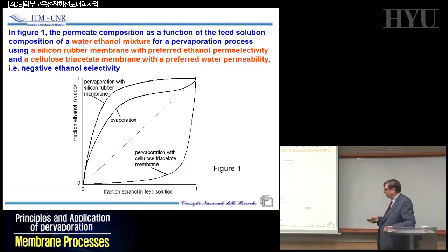This kind of process is utilized today in some areas. It's not standard. There are no big plants, but in the pharmaceutical industry, in the cosmetic industry, if you want to produce, for example, isopropyl alcohol, or you want to recover isopropyl alcohol, which is used for the extraction of different components, or you want to produce very soft, expensive cream for ladies with acetone, basically ultra pure acetone, with no water at all to avoid the formation of any emulsion, etc. This technology is utilized today on a large scale.